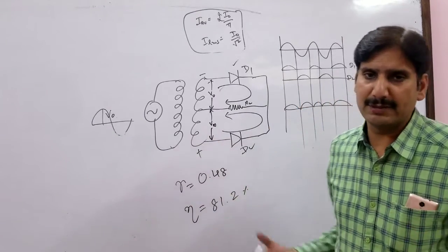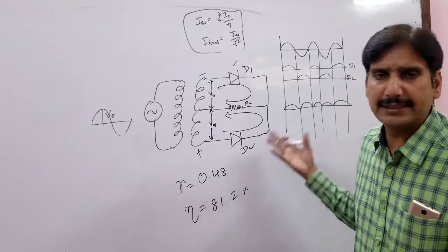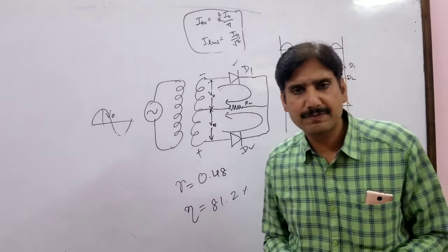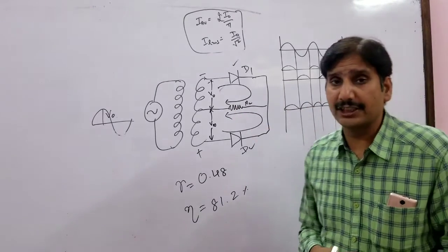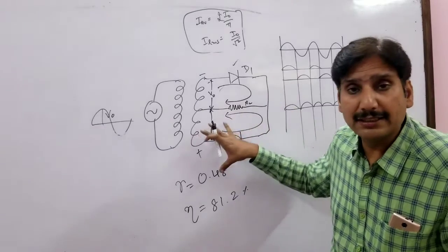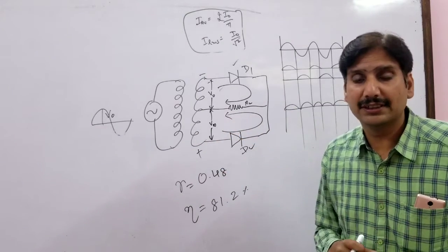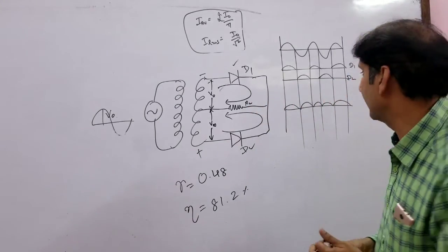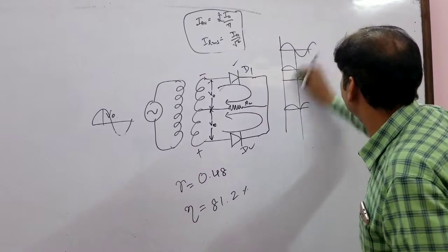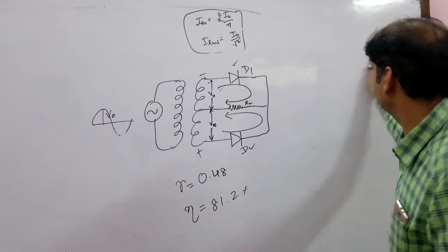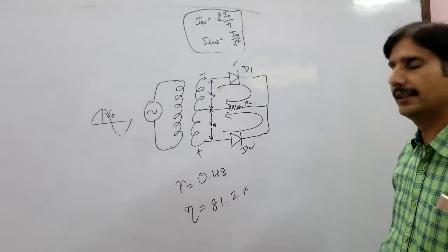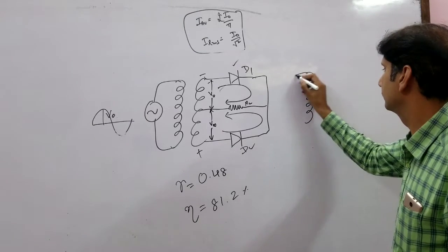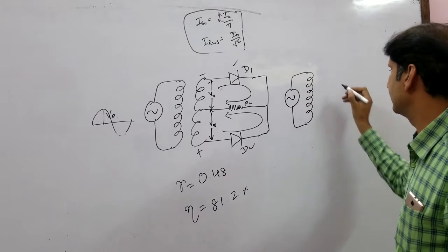That was just for theoretical purpose to understand the concept of rectification. Otherwise, half wave rectifiers are hardly ever used. However, full wave rectification can be done using this method or using a new kind of circuit, which is what we call a bridge rectifier. I'll draw the circuit diagram for the bridge rectifier. This is the input AC signal.